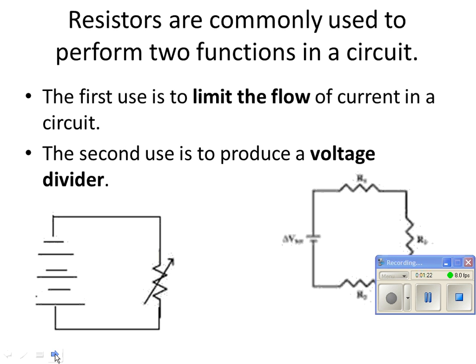Okay, now a series circuit, as you know, has two purposes for putting a resistor in there. The number one purpose is to reduce the current. Now look at the drawing on the bottom left and imagine that that is a 0 to 500 ohm resistor and that you have a 12-volt battery supplying this. So how much current will flow at 1 ohm and 12 volts? How much current is going to flow?